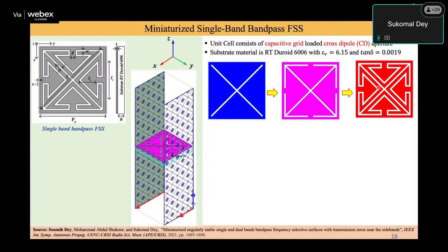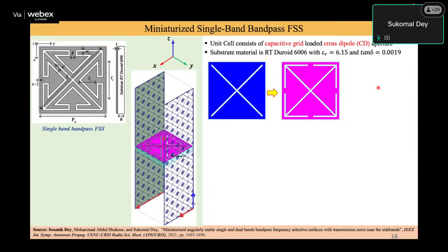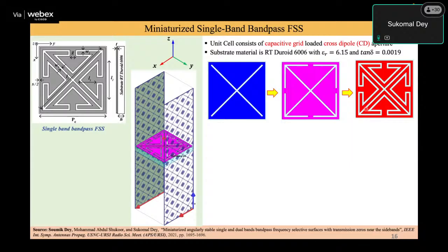Clear? Step by step process. First, you have to add capacitance, a little more capacitance. Whenever you add a little more capacitance, some inductance comes from the metal, from the violet color parts. White is always a gap. From the violet, you get a little amount of inductance. To give more inductance, you have to make more lines in it. That is the way. And why are you making it like this? To make the structure as compact as possible.